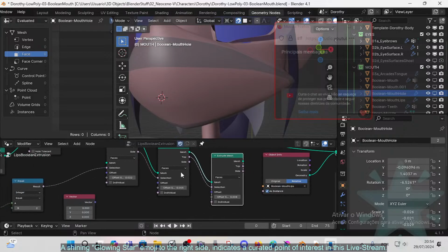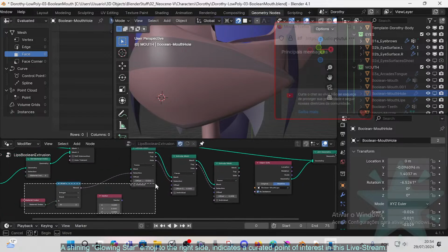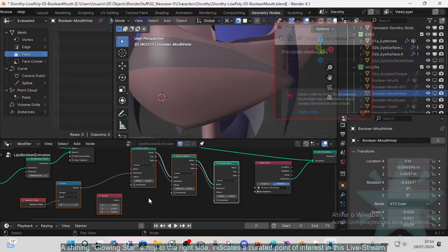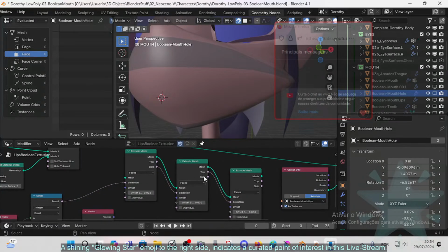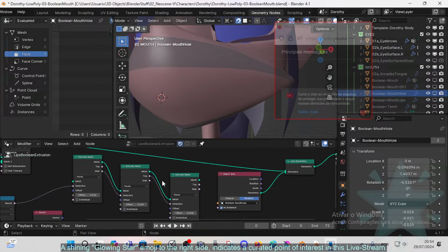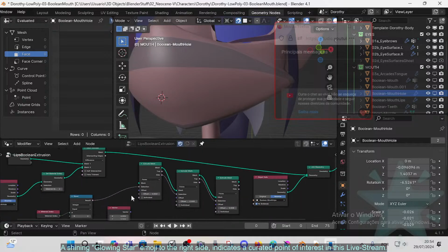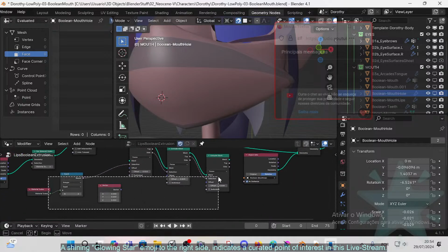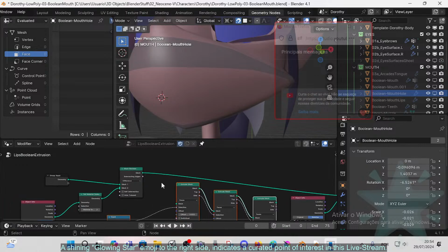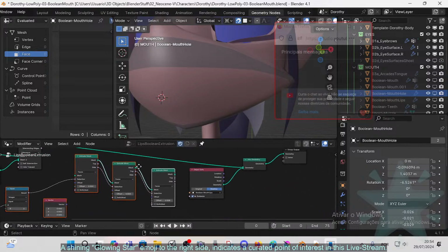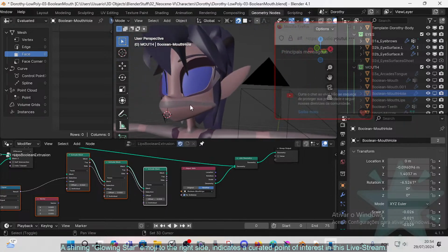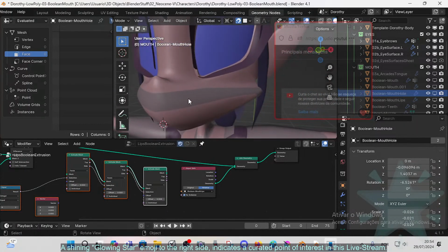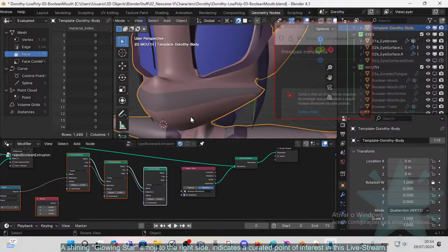And then this was another experiment that I'm doing, trying to make organic lips procedural, but no, never mind. I was studying geometry nodes a little. I've never studied that, and apparently this is not trivial. It doesn't seem worth it. There's a limitation currently in geometry nodes that we cannot edit the procedurally output mesh directly. So this is very, very limiting.